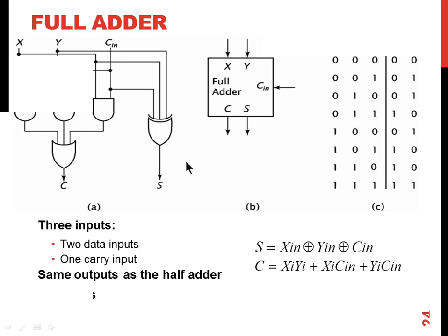The basic form of adder, now if you look at it, is a ripple carry adder. So here we have two inputs A and B. Each input is 16 bits, 15 down to 0. And adder is represented for each bit of the input. So A0 plus B0 will be done by the 0th stage of the adder. And A1 and B1 will be added by the first stage of the adder. And so on till the 15th stage of the adder.